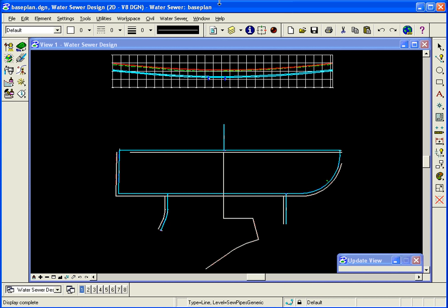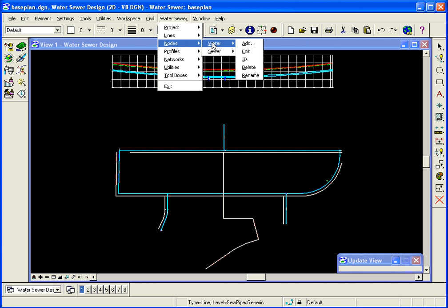Now that we've come to the point where we're going to add sewer nodes on page 1-17 in our manual, I'm going to go ahead and bring up the sewer node dialog. Sewer nodes are a little bit different than water nodes in the fact that sewer nodes is where we actually place elevation on the nodes, therefore helping to determine the inverts of the pipes coming in and out of the nodes. So we place a top and bottom elevation on the sewer node.